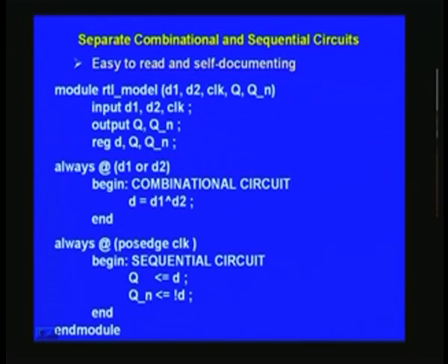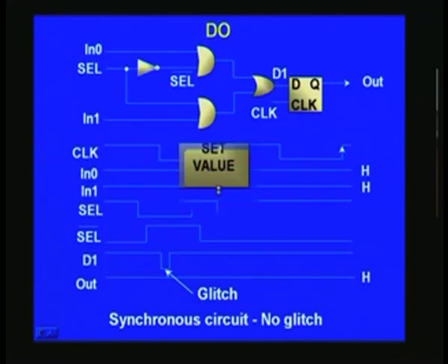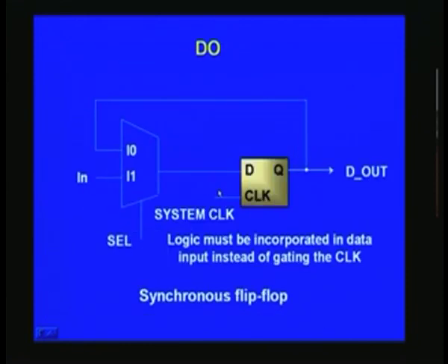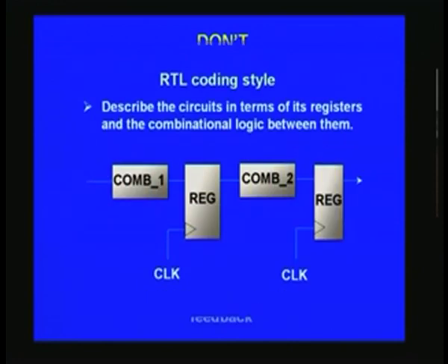Earlier we have seen how the basic RTL coding style will follow the pattern, as depicted in this figure. First combinational, then register that, and then follow it by another combinational, register, and so on. This is how data flows as such. So it flows from one point here, and then it flows to this, and then sets down here, and so on. It keeps on going stage after stage, and so it is the same pattern that we have followed in that particular code which we have.